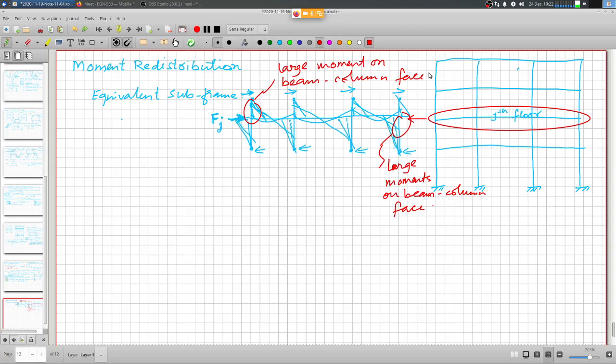Although in analysis you perform gravity load analysis separately and seismic analysis separately using different section properties, because for the earthquake analysis you do need to take into account the reality of extensive cracking in the section, and the cover not being available. So you only take into account the confined core, and that reduces the stiffness, that reduces the forces that will come on to the structure.